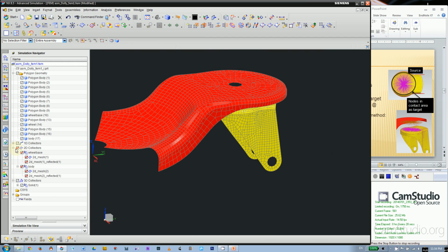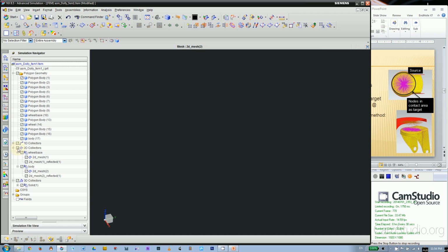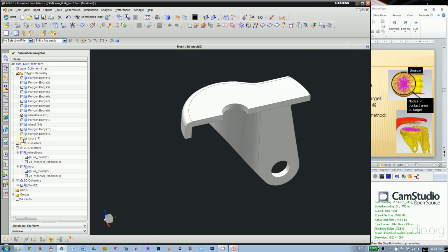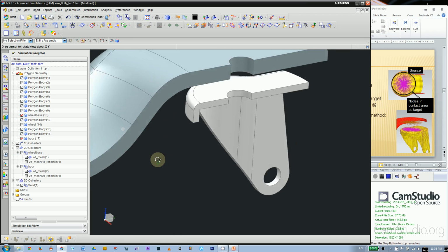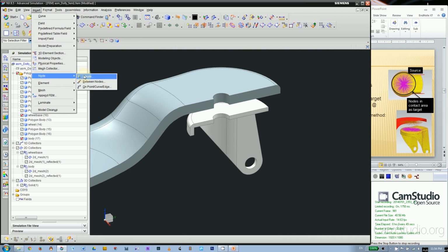And again, we needed to insert some spiders, and before that, we need to insert the center node for the spider. And so we need polygons. That's the polygon for the wheelbase, that's for the body. And then we're going to insert node and create.